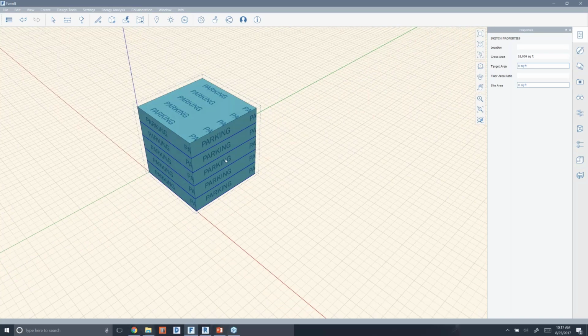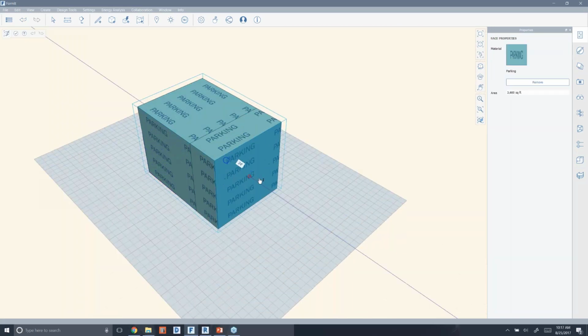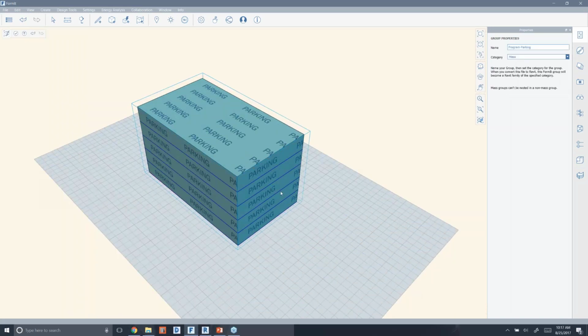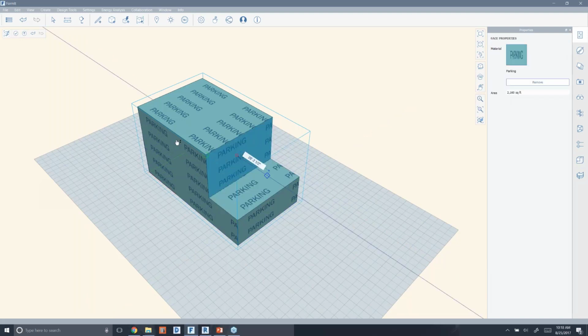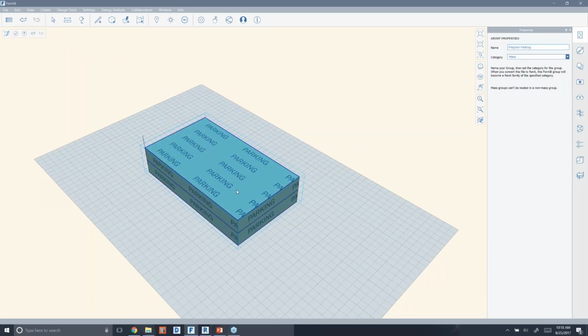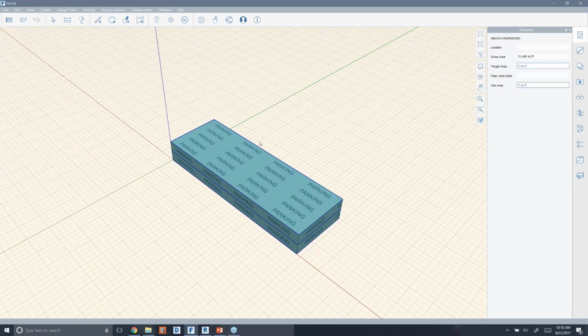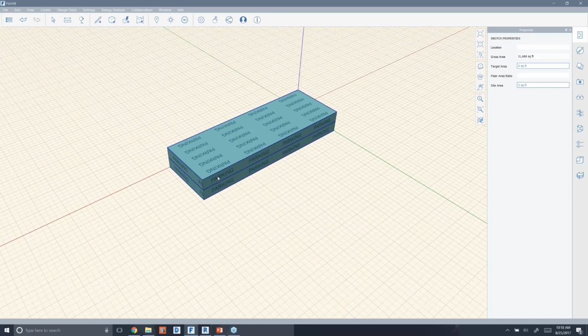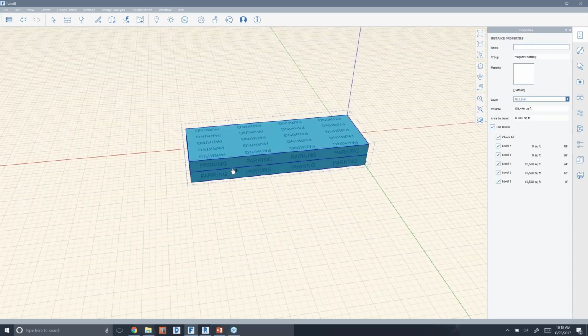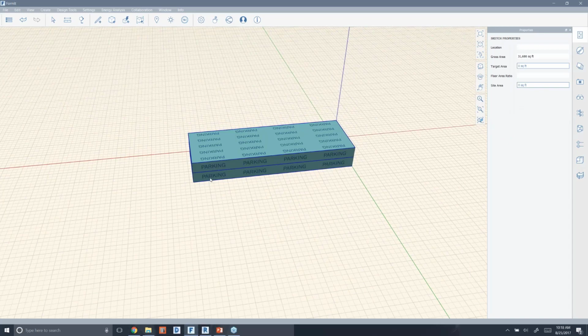And once you place this cube, you can edit it by clicking a face, dragging it out. You can also sketch on it. So I can draw here, use the level lines as a snap candidate, and then click that face and push it off, because I know I only want to have 2 levels of parking. I can continue to adjust this and then click off into space. And I've got my parking cube, and the area is all updated with it.